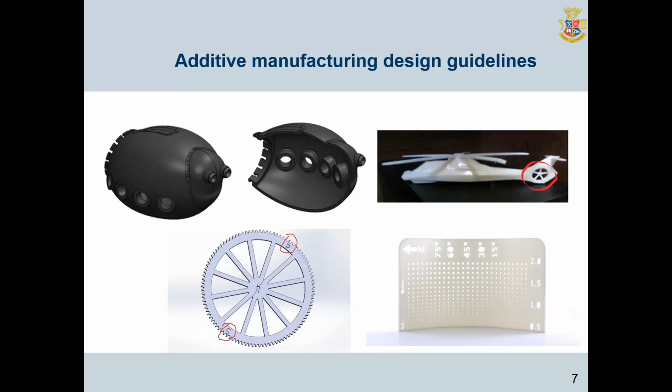There is also a software side of the problem. Not every slicer correctly handles internal dimensions, so it is better to increase the diameter of the holes. When modeling, it is also necessary to take into account the maximum possible dimensions of the printing space. If the model is larger than the dimensions, then it must be cut in order to print in parts.